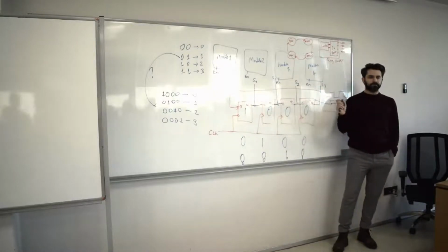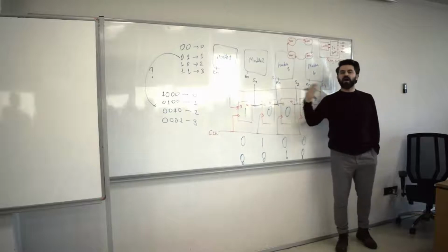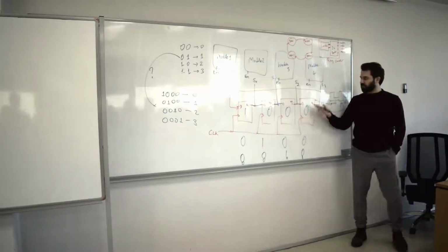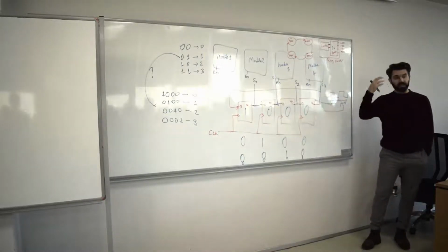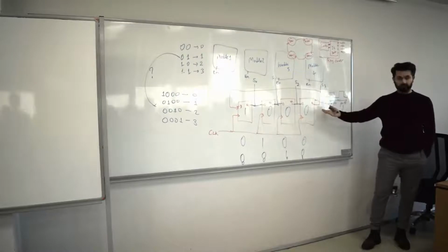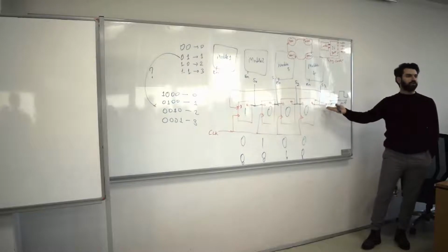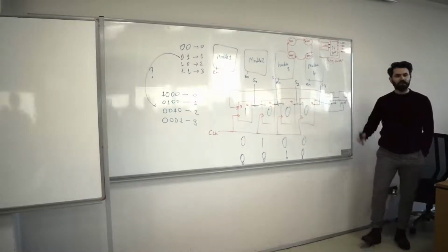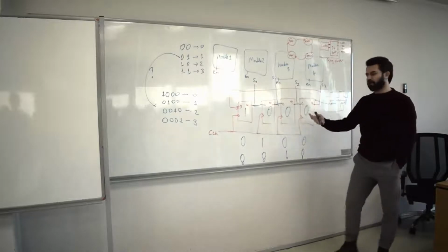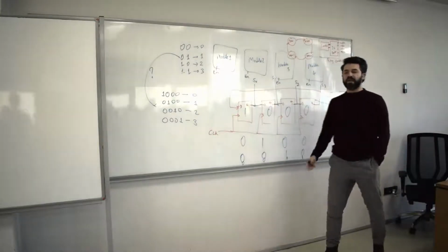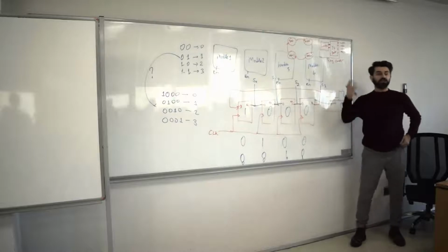Okay? So people devised different approaches to this problem while keeping the complexity in mind, because without any gates, your complexity is reduced. There's no combinational circuit here. It's all sequential circuit elements, right? The flip-flops. So people thought about that. They gave a lot of thought to this, and they finally came up with the Johnson counter.